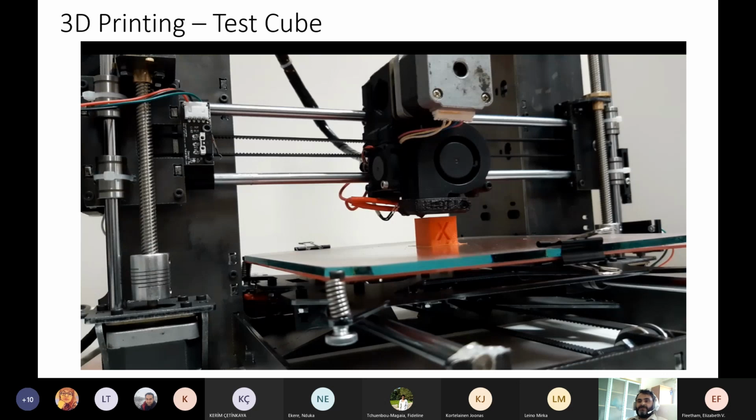As the height of the part we are printing increases, the part may be cooled by airflow coming from the sides of the printer. The 3D printer actually doesn't have any side plates to stop this airflow. It's completely an open system. Therefore, the most accurate printing is done close to the table, where the part is kept at a relatively even temperature. So when the part is small, this type of printer gives better results. The larger the part, the more important it becomes that the part is well designed and takes into account thermal shrinkage in the plastic.